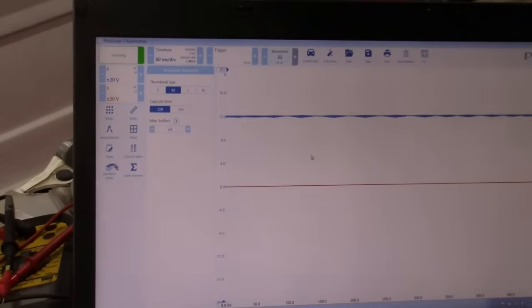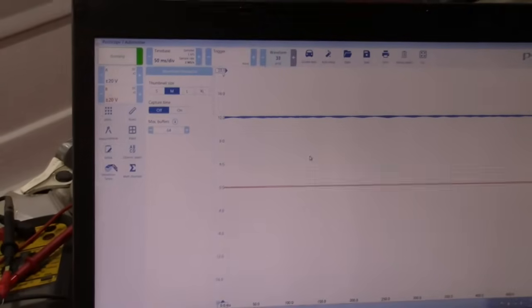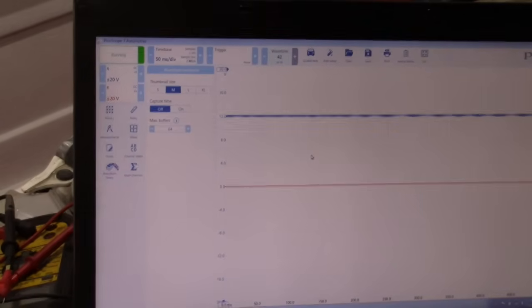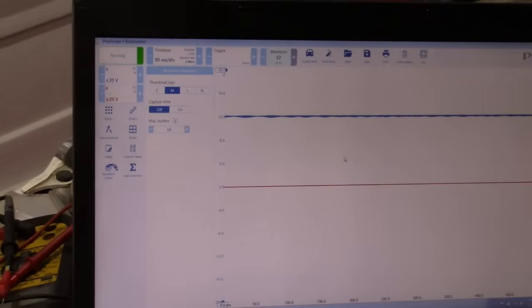So, boy, you see how handy having the scope is when you've got things that are just a little difficult to interpret. So that tells us that we do have an ignition input signal going in there, and this coil is still not firing. So what does that tell us about our sensors, the CKP, CMP, and TDC? Those must be working. You know, while we've got this scope hooked up, let's just test one of those, because we know that that is not going to be expected to be a square wave signal.